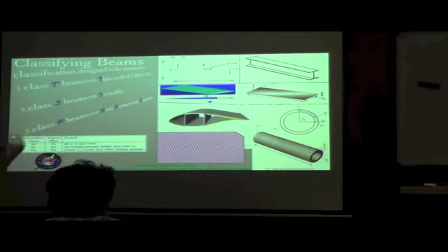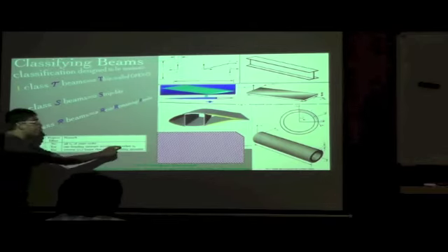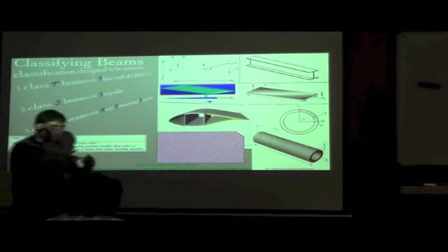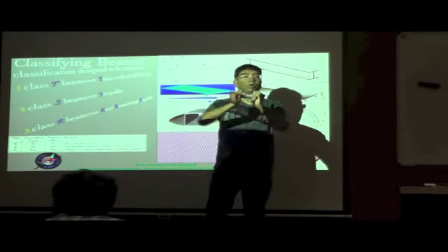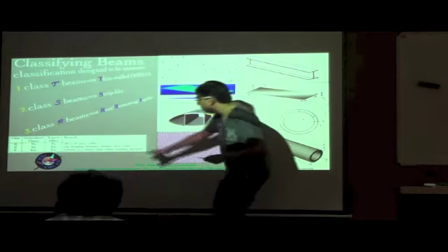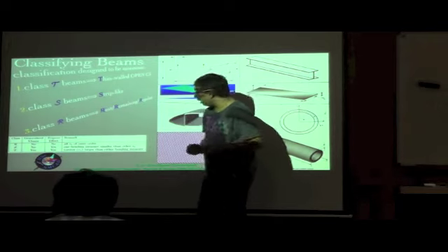So the T-class beams, as far as torsion is concerned, become the most complex because they have nonlinear effects and they have the restrained warping effects. In other words, the 1D modeling is going to be complicated because they have more boundary conditions than you would otherwise expect, because of the presence of kappa 1 prime in your 1D theory. In the case of S-class beams, one bending measure is smaller than the other kappa i. Basically kappa 1 is large, kappa 2 is large, but kappa 3 is small. In other words, kappa 3 is smaller compared to kappa 1 and kappa 2.